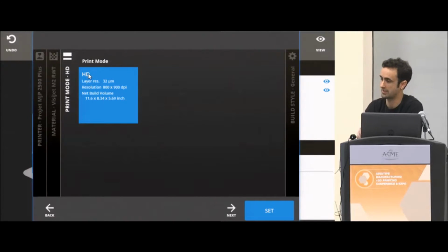And I designed a part so that it's supportless printing. I've done a lot of things where it took a little bit longer up front to design a part that prints without supports, so I can avoid having to sand things off and avoid having to refine areas. Versus if I just throw a part in the machine and click print, I might get it right away, and it might be really easy for my designers to just do that, but the overall outcome is now I've got to pay someone to sit there and sand out the inside of this part, or machine out the inside, and what if it's got a bend in it? Or what if it's a U shape, or something complex, which you can't machine out.